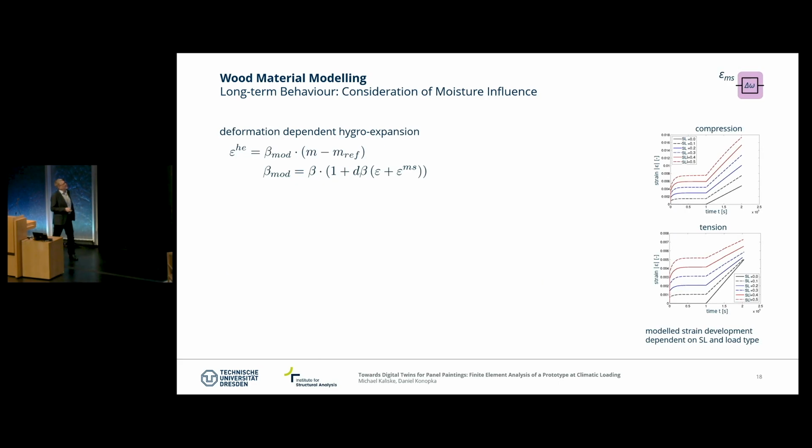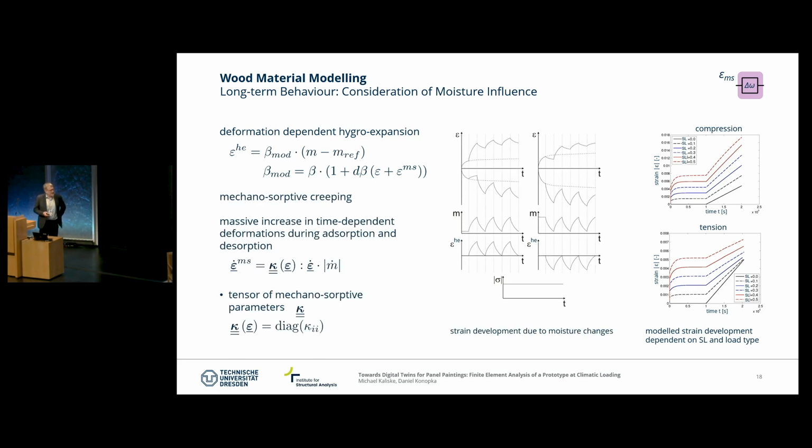So then we have here the hygroexpansion, the deformation-dependent hygroexpansion, which has to be characterized. We have a distinction between compression and tension. And the mechanosorptive creeping has to be accounted for, which is an increase of the strain even at constant stresses, but at a cyclic or changing moisture content.